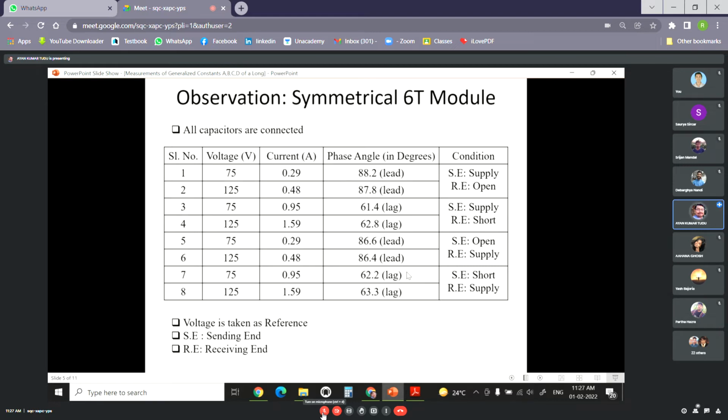It is very difficult to maintain this balance because of the unpredictable demands of the consumers, so an unbalance always exists between the supply and demand of reactive power, and there is always a variation of voltages from their respective values.